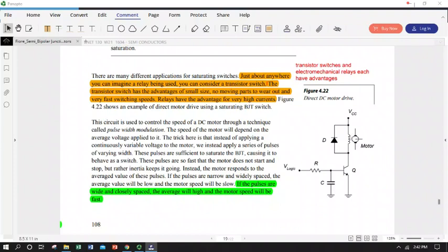Then it in turn is enabling a solenoid, which perhaps is actuating a relay, which can turn a motor on. So very small current controls somewhat larger current, which controls ultimately very large current. And that cascading small to large current is very characteristic of how you will design and troubleshoot switches in an industrial setting as an electronics technician.